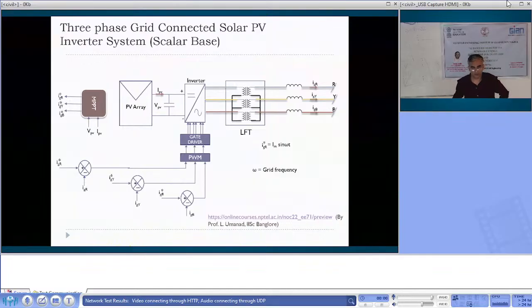You have shown a lot of switching, right? In practice, do you achieve the switching perfectly, or can harmonics be injected by imperfect switching? Imperfect means we have to give some delay. Because when we are turning off a switch and turning on the other switch in the same leg, you have to give some delay. The delay will give some imperfection, but very little. It's not noticeable much, but still we can analyze that also.